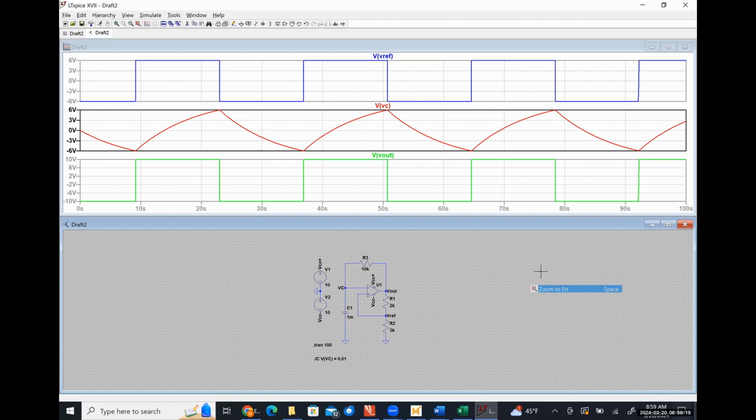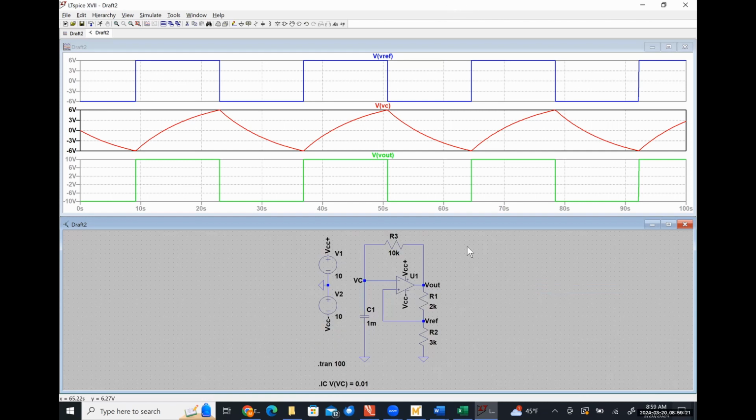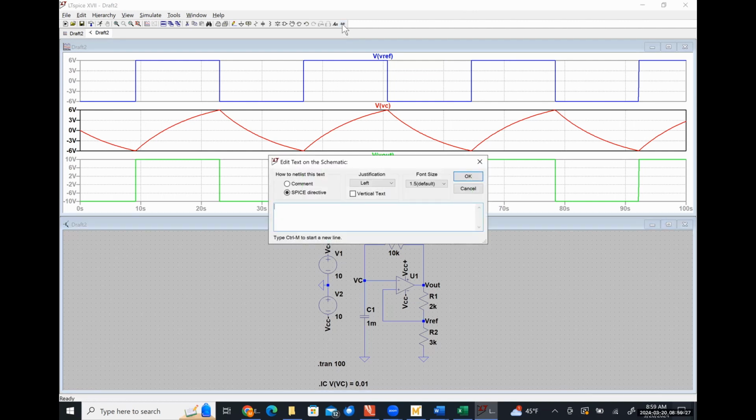Sure. So let me get this thing out of the way. This .op command is how we enter in SPICE code. And we're going to be using initial condition statements very, very soon when we're looking at transient analysis of problems. And I believe I used this statement when we looked at a simple transient analysis circuit on the first day of class as well.